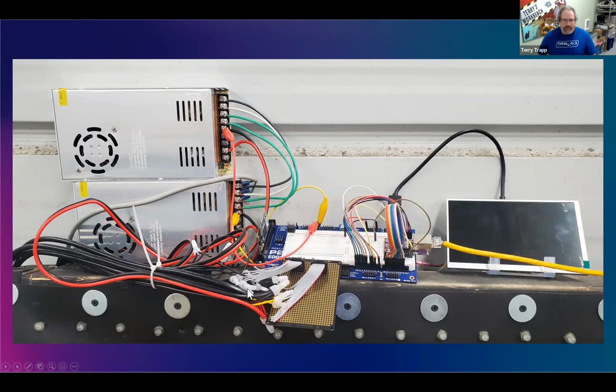One of the problems that I ran into early on, and I'm probably going to put a set of buffer chips out here for this, is you have to ensure that your ground goes directly to the ground on the power supplies for the pixels. If you connect it just to one and you have them paralleled, that's not good enough because it will interfere with the data stream, and you'll get flashies and interference with the pixels. So you have to make sure that you have no ground loops for this to work properly.